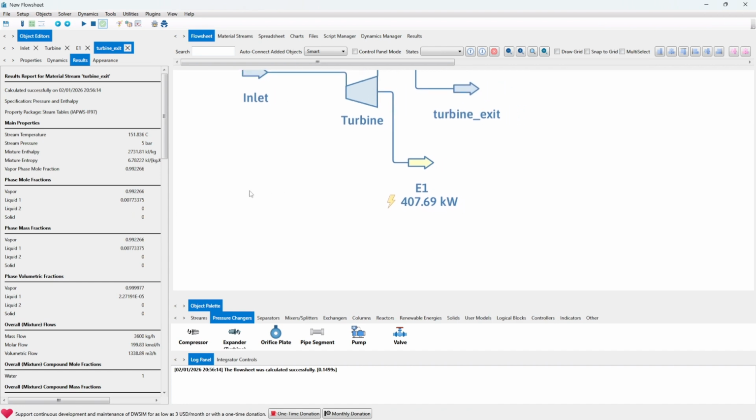In order to go to the pump, because I think that's the difference between Rankine and Carnot, setup wise, there is a pump involved. The pump works only with liquids, pure liquids. So you need the vapor fraction, the quality, to be 0, to be purely liquid.